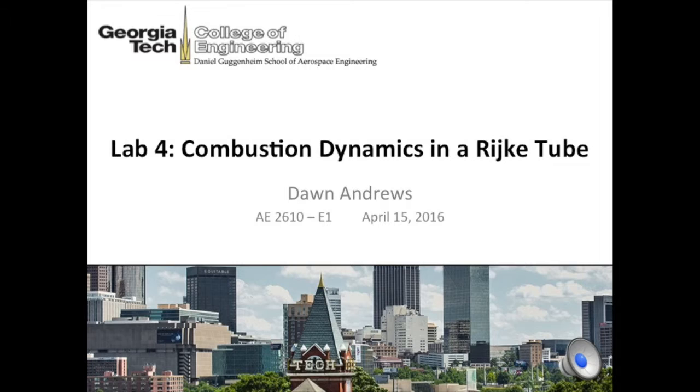The focus of this experiment will be an investigation into the amplitude, frequency, and phase angles that result from different heat source locations. We will also be able to gain a deeper understanding of the other equipment involved. On this next slide, the experiment was held in the ESM Building Combustion Lab, which is home to a 6-foot Rijke tube. This Rijke tube is attached to a pulse combustor as the heat source and has a few different methods of measuring the combustion dynamics.